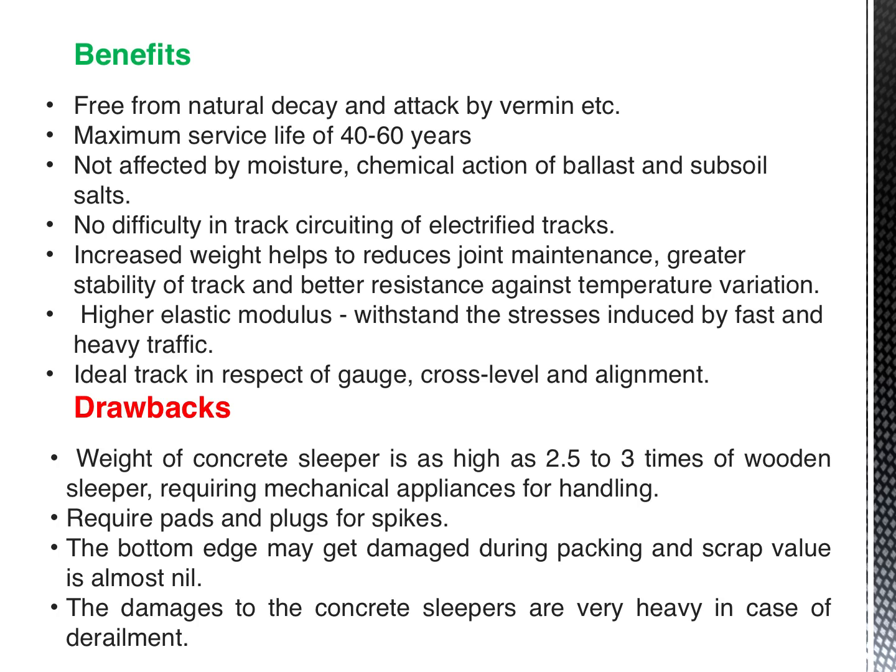The weight of one concrete sleeper is almost equivalent to 2.5 to 3 times that of a wooden sleeper. Handling is a little difficult, and mechanical appliances are required for handling concrete sleepers. These require pads and pucks for the spikes, and the concrete sleepers are also expected to get damaged at the bottom edge during the packing process, and the scrap value is almost nil.